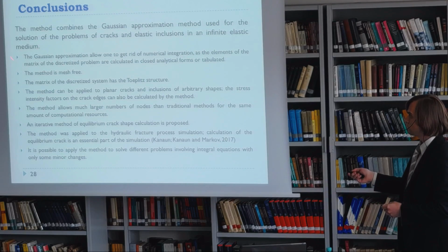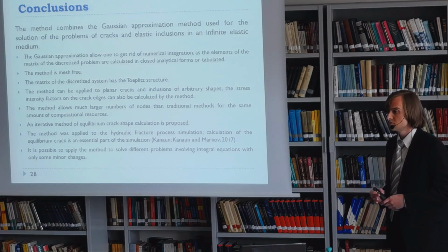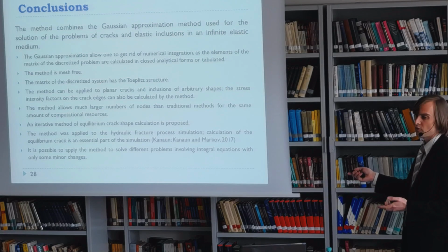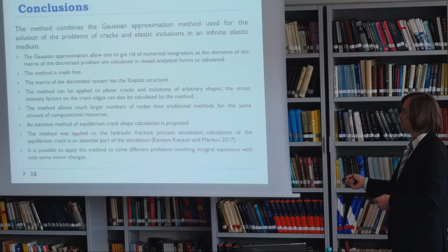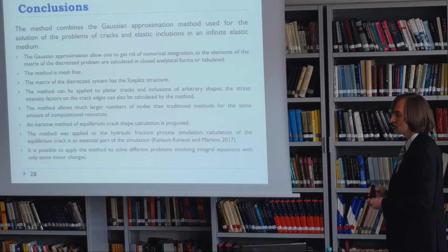The huge advantage of this method is that the Gaussian approximation allows us to get rid of numerical integration altogether, so it improves the efficiency. And of course, for example, for this hydraulic fracture simulation, we need to solve this problem a lot of times, and it is a huge advantage. The method is mesh free, which belongs to this branch of numerical methods. The matrix of the discretized system would have the triplet structure, which is an obvious advantage.